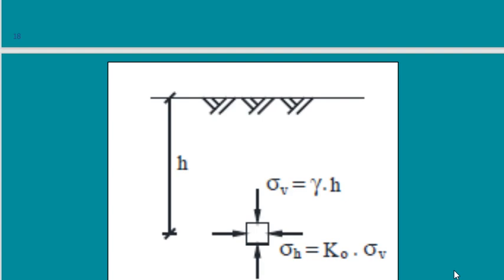So why put all of these stirrups? Because there are lots of horizontal stresses on the column. So it's the same. Here I have vertical stresses, so part of these vertical stresses will act as a horizontal stress.